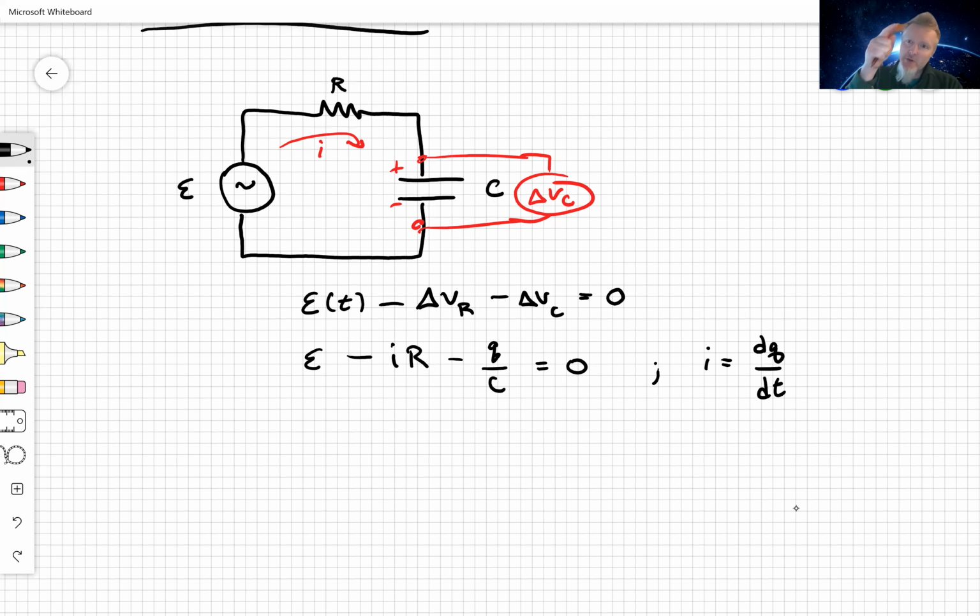The power source is then going to reverse the current, and the charge is then going to start coming off the capacitor. But notice that there's a lag now. If you think of the charge on the capacitor, it was at its peak when the voltage of the source was 0.